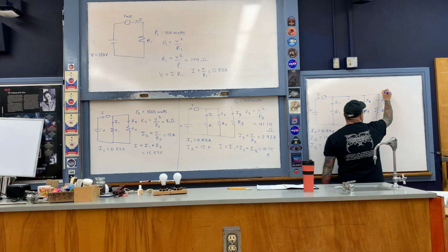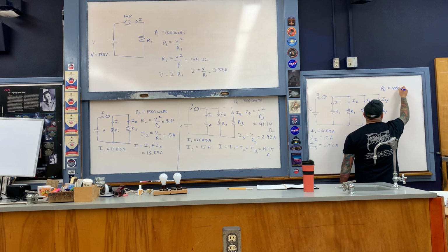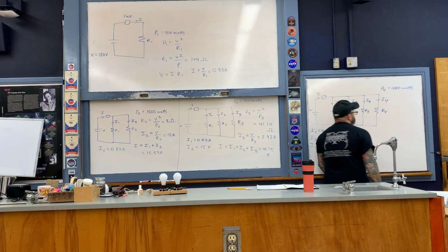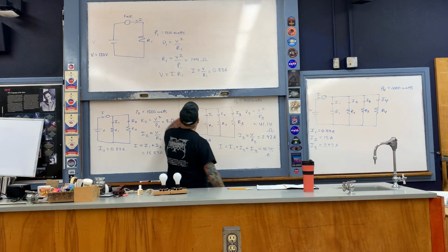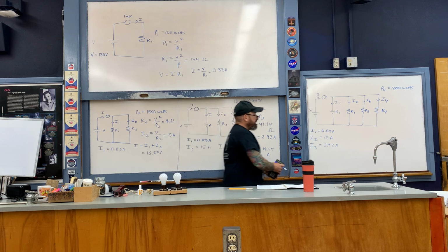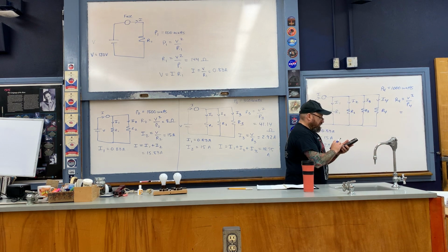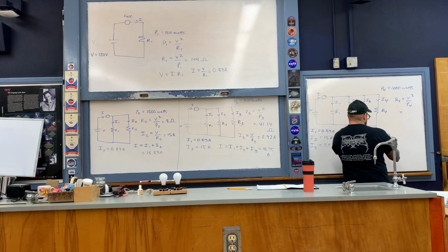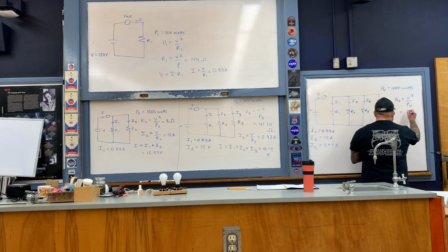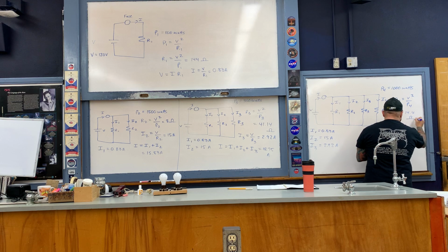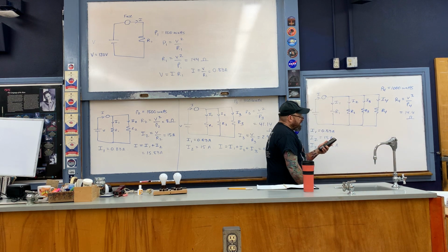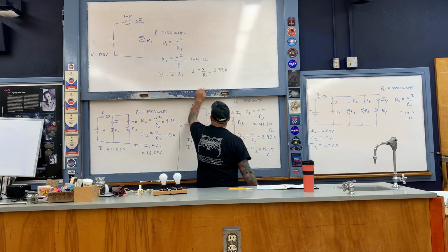This last device here, the hair dryer, has a power associated with it equal to 1,000 watts. So now let's go ahead and find the resistance R4. In order to do so, we'll use this expression here once again. So R4 is equal to the voltage squared divided by P4. So 120 squared, and then divide that by 1,000, and that comes out to be 14.4 ohms, like so.